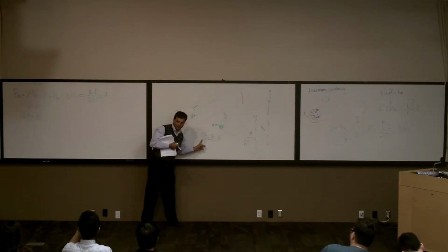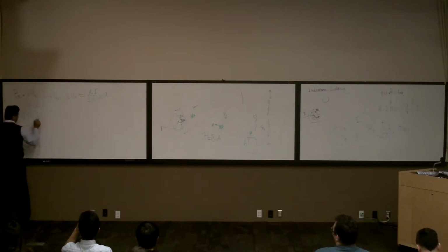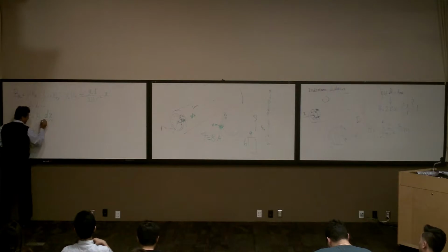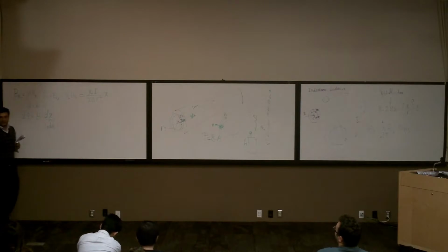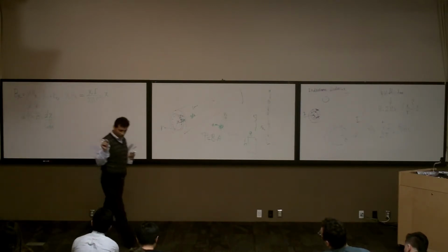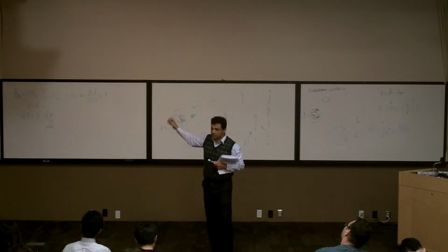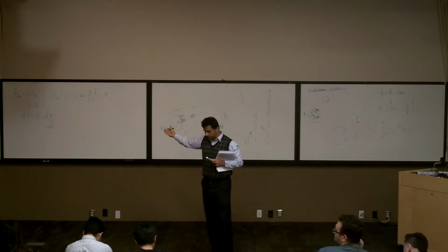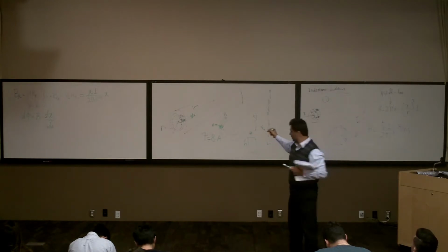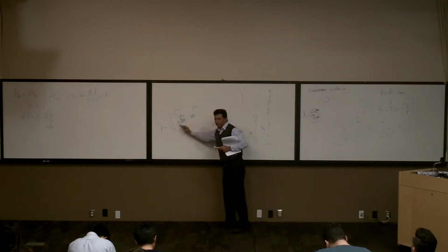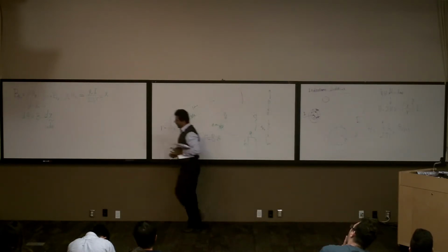How much is my flux d phi? It's going to be B times dx, right? So d phi is going to be B times dx. Be careful. This dx has been 1 times dx, because dx by itself is a length. It's not a square area. Don't get it wrong. It's 1 meter times dx, which the unit is going to be a square meter. Just follow the dimension. My point is, it should be a square meter. And because we are calculating for the unit length, you put 1, and you don't see the 1 over there. Now I have the phi.